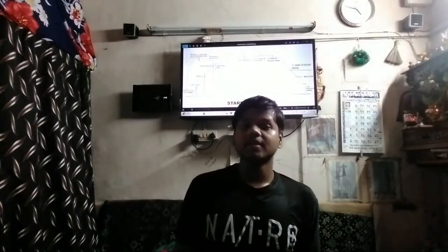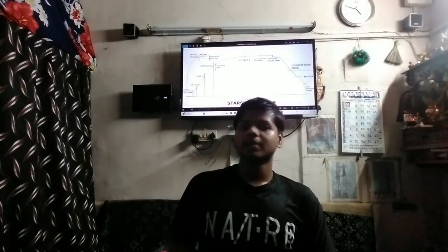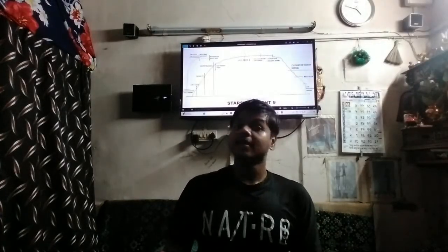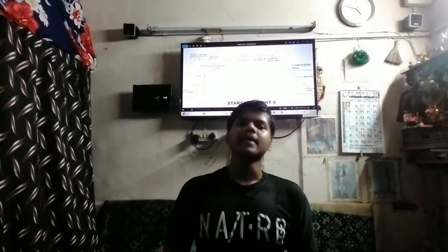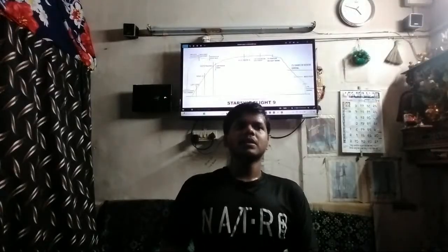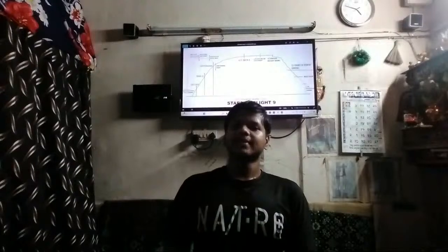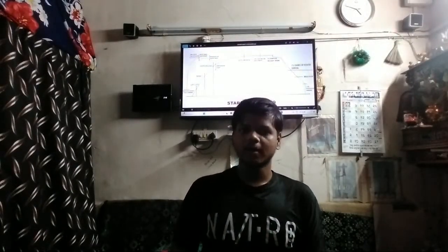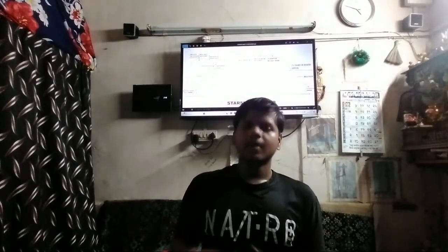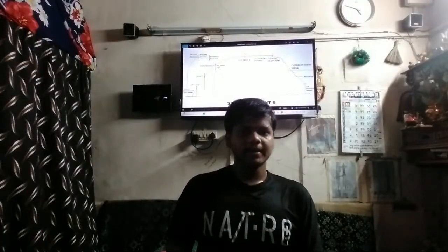But the higher angle of attack will be performed by booster 14-2 during its re-entry to reduce the descent velocity and increase the atmospheric drag, as we know, for descending and lowering our velocity. So it will save us more fuel during the landing burn if the engines go out and it performs a nominal landing burn.